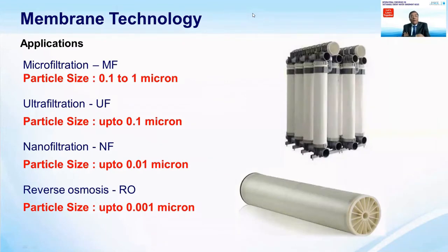Now, we have different applications and different types of RO membranes for different applications. As I have already explained, a membrane is a molecular sieve: molecules of a certain size can pass, and that depends upon the size. The smallest hole in the membrane, for easy understanding, has a particle size of up to 0.001 micron. It is for RO.